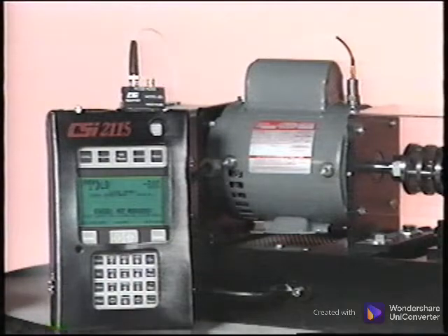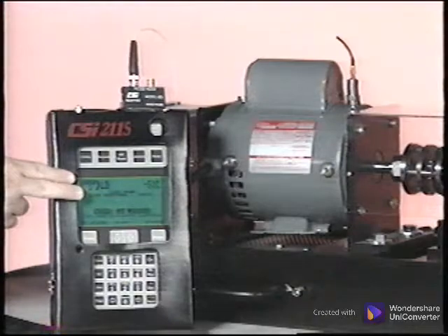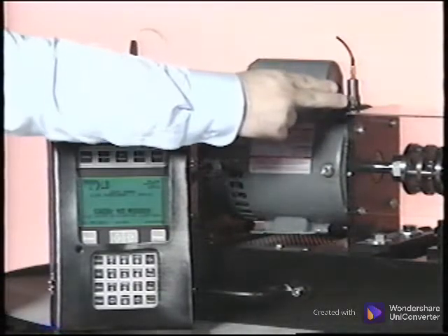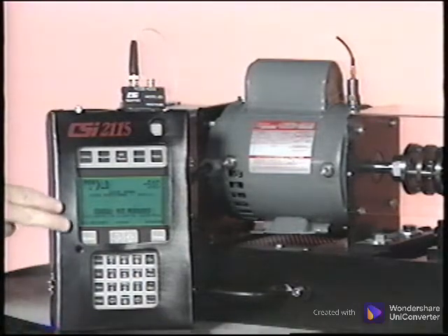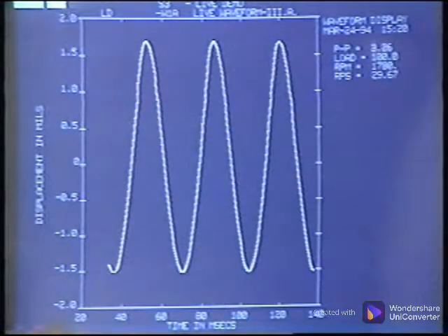The waveform is really a continuous signal that the vibration sensor sees. But most of today's analyzers are digital units, which means they use an analog to digital, or AD, conversion to manipulate and store the data. The analog signal then must be sampled with enough points to store a good representation of the actual waveform. This waveform is a stored digitized waveform. The actual stored points have been connected by lines, but the cursor only lands on the digitized stored points.